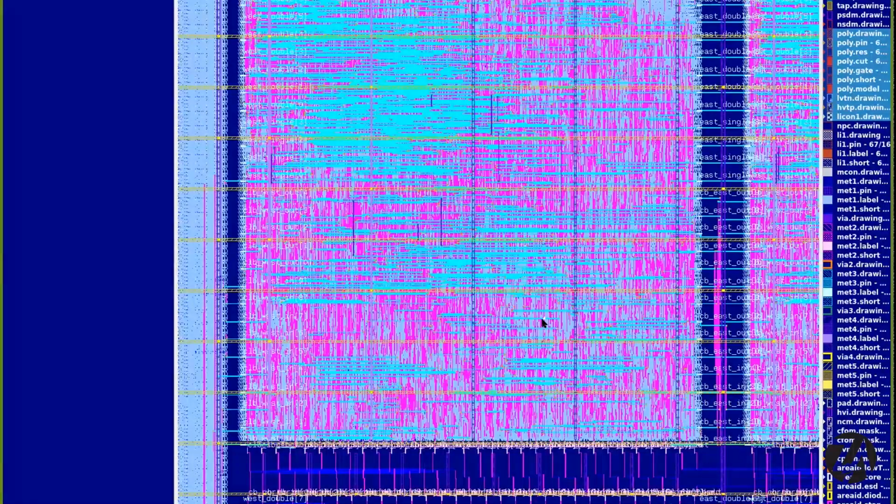And just by adding 2 small custom standard cells, which get rid of unnecessary buffering because you know the inputs and outputs, I think they got almost a 2x improvement in performance. In terms of speed or size? In terms of speed. The whole thing was a lot smaller and the delays were much lower. And it came very close to commercially competitive, in the sense that it could compete with an equivalent commercial chip.